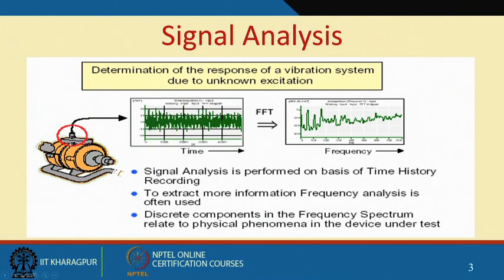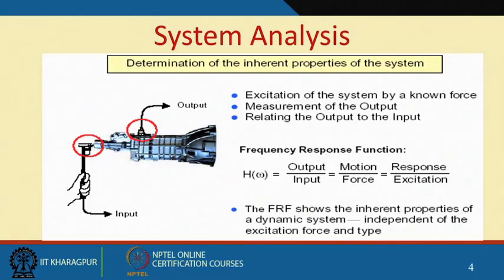in the time domain, which has been measured from this motor with the transducer. And later on we will go into the frequency response of this signal. So, every peak here corresponds to a particular component here. But that is something we will discuss in the next lecture. Even in the time domain, many features can be measured and analyzed, so that they give us some clue as to what is wrong with this machine.